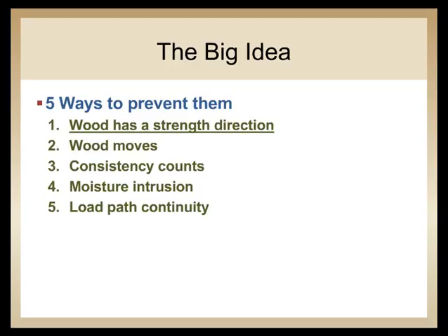So first, and most importantly, wood has a strength direction. 2, we need to realize that wood does move and to account for that in our design and framing. 3, consistency is very important. And 4, moisture intrusion needs to be minimized. 5, load path continuity is key.